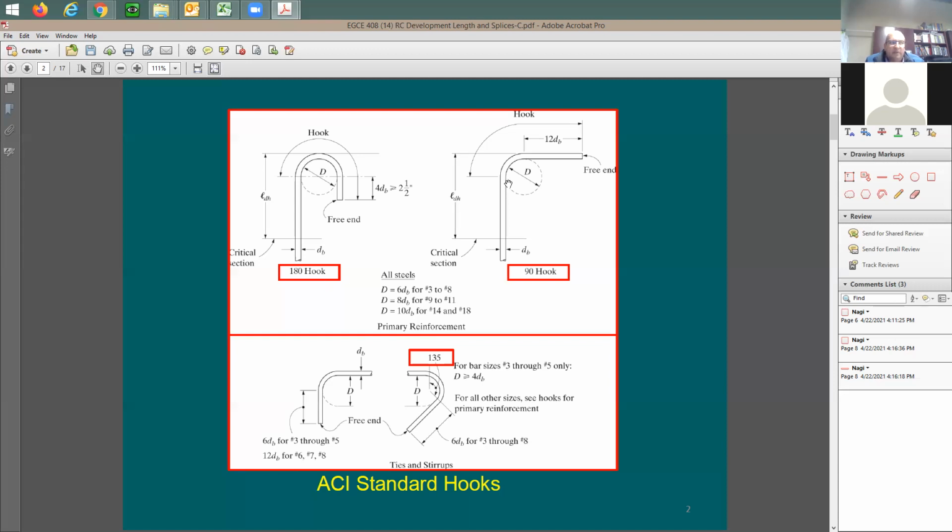If there's a chance to do the 90-degree, do it. Don't do the 180, because 180 needs a little bit more work in the machine, right? You need to have a bender, like a bender machine. And in order for you to do this, it's going to take a little bit more effort and time.